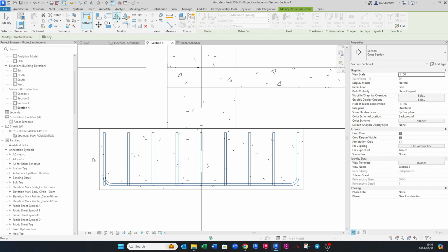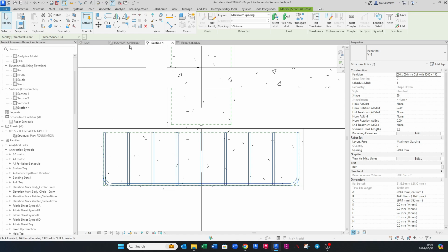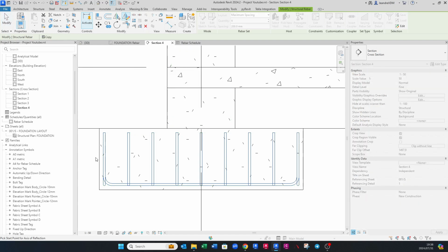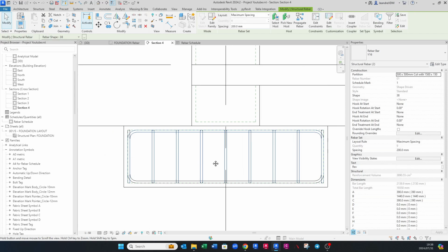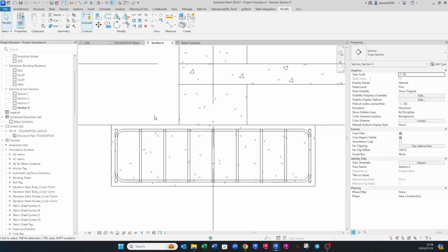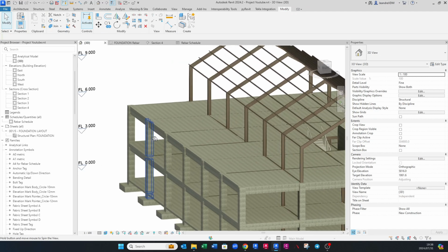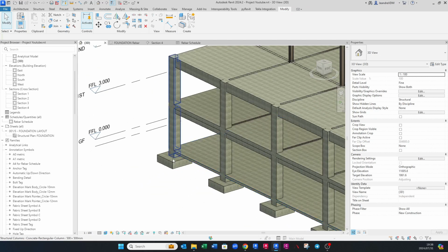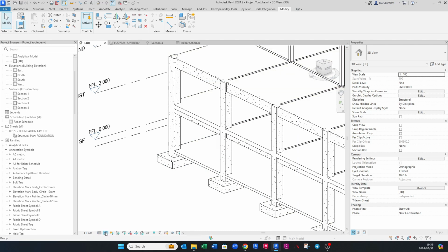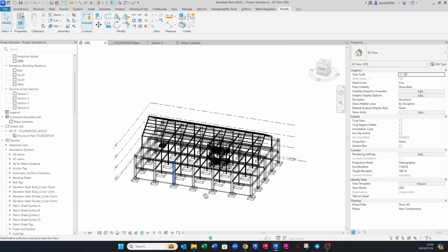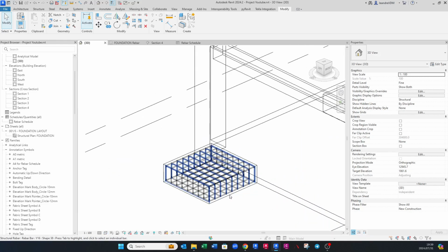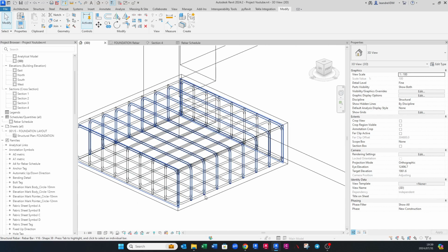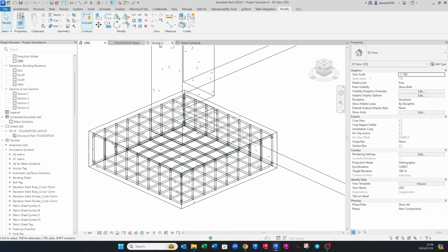Apologies, this is only when you have an axis already. We don't have an axis to mirror around. We will go to DM, draw axis, mirror. So then it snaps to this midpoint and we just mirror it. So you can see that that has been mirrored. So let's go to the 3D and check how this reinforcing looks like. Just put it on wireframe and we just go and find this specific reinforcing. And there you have your cage, which is quite neatly set up.